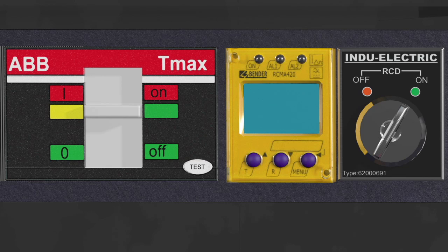Adjustable residual current monitors have proven to be a reliable line protection solution. For our power distribution boxes, we are using the Bender Residual Current Monitor RCM420. It reliably protects the installation from these unwanted power outages. In addition, its built-in display indicates the sum of all fault and leakage currents within the entire installation. Suitable threshold values for any given event can be easily set on site.